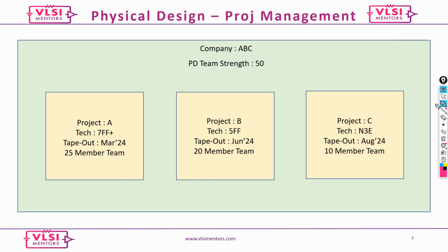Okay, and the next question is what should be the timing number after the route stage. It should be clean, ideally speaking. Otherwise, I always look at it like the WNS should be less than your uncertainty value. That's the kind of thing that we look at.